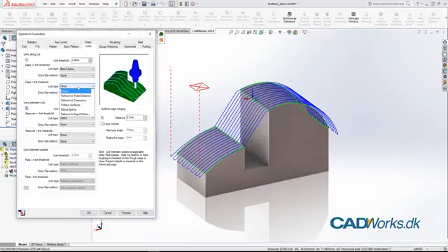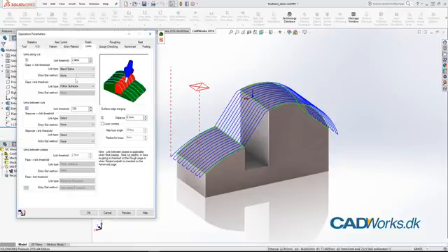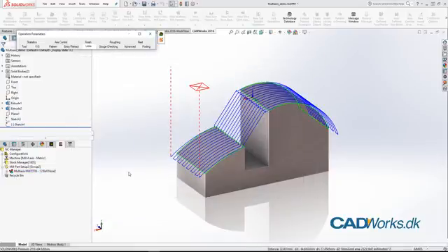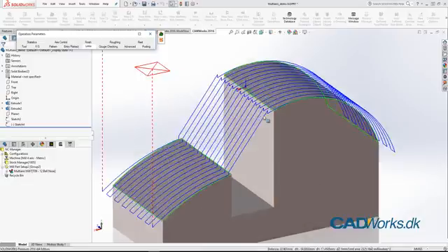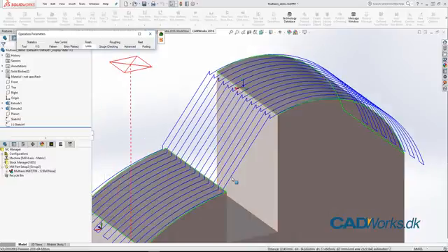The first one is the direct. This is what we have right now. And actually, if I have follow surfaces, I'm going to skip that. In this case, it will do exactly the same as the direct. But I can go retract to feed distance. And this is one that we should have a look at. So I'm going to update the toolpath, and you can see that we come over the top and then we retract in feed and then feed down, feed in, and start the milling path again.